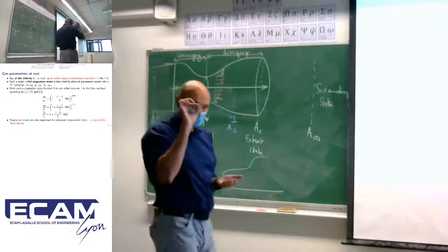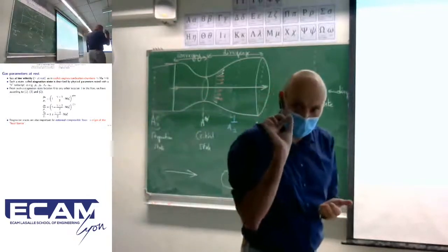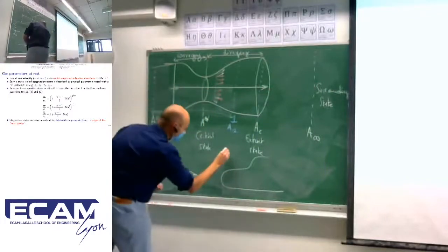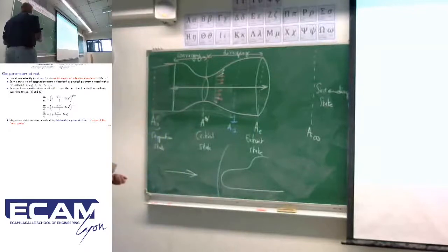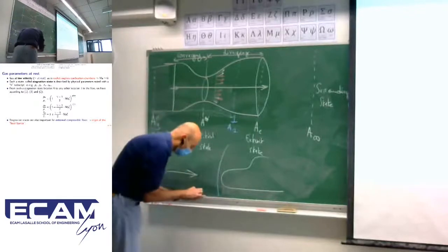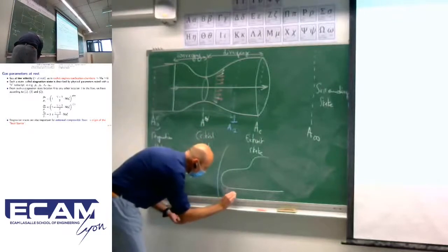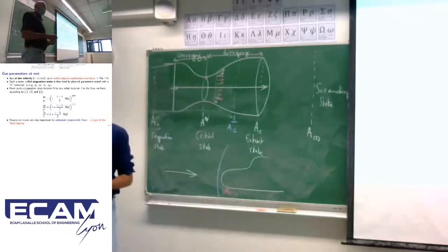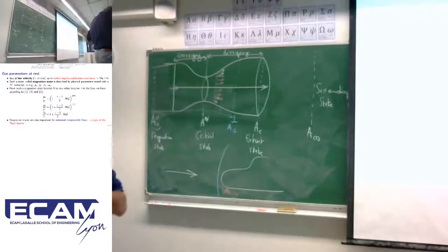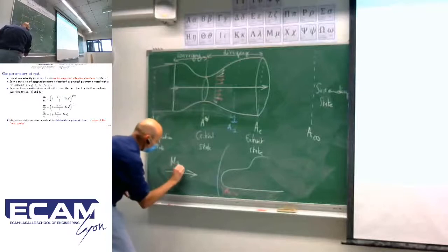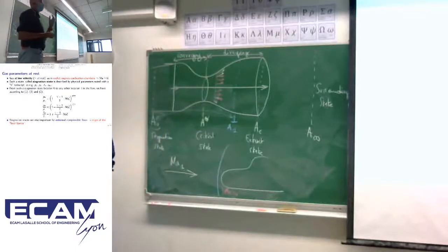And if you are getting into a location which is really close to the wall, you will create a shock wave. We already saw that last week, a shock wave that looks like this. And after this shock wave, it's possible to find a location where the Mach number is really close to 0. It's called the ram effect. So you are just decreasing the speed in order to reach some position which is really close to a rest position. But you were starting from a Mach number here that is really larger than 1.